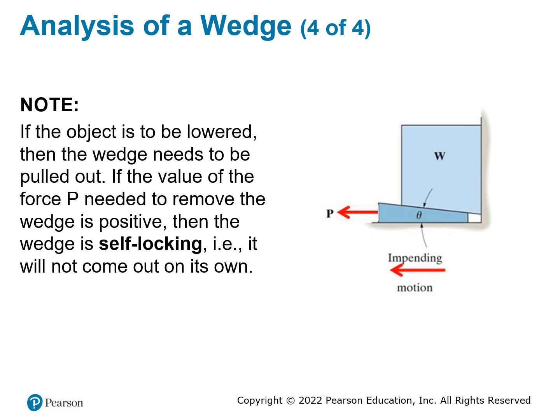There's an idea called self-locking, which means if we don't push this one, once you slide this wedge in and remove this force here, it will be locked. It would be locked simply because the friction force prevents it from moving, and that is what we call self-locking.